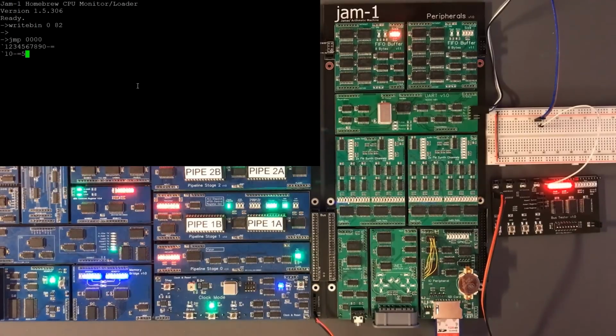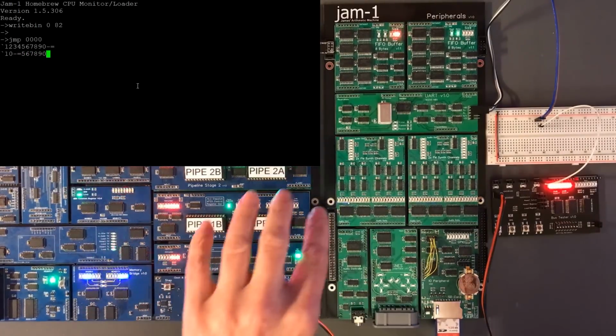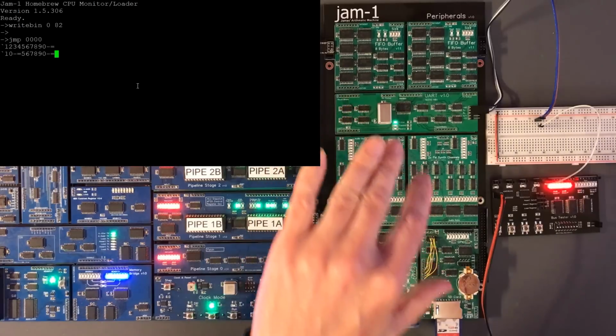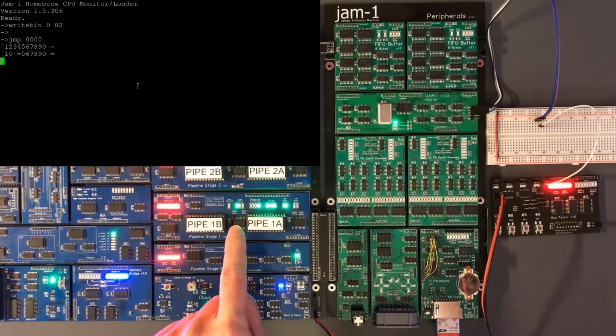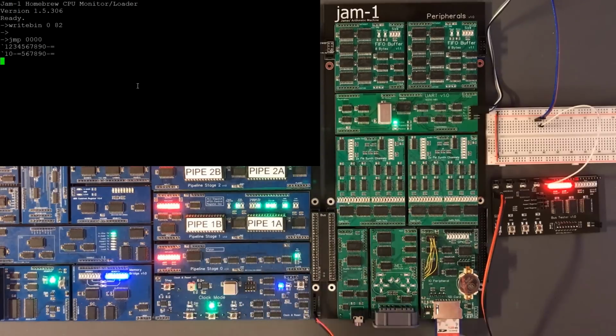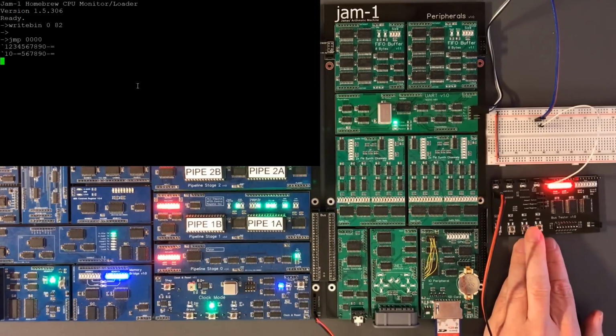And now we're seeing the system pulling those bytes in one at a time. And once again, the last few characters are correct, but the earlier characters are overwritten by later characters when we overfilled the 8 bytes of buffer capacity. So still running at low speed, let's see if we can make this work by using the clear to send signal.